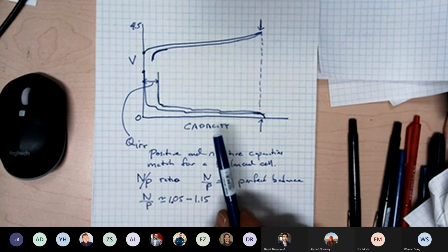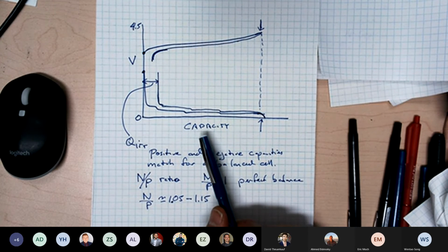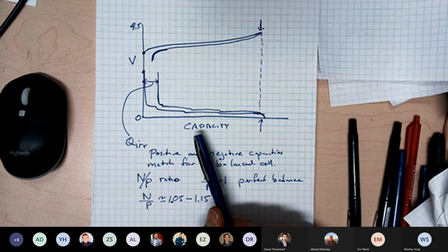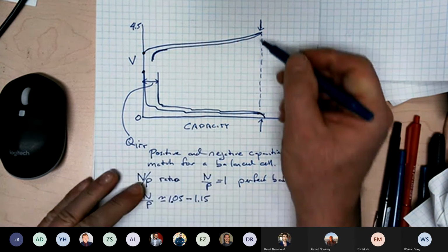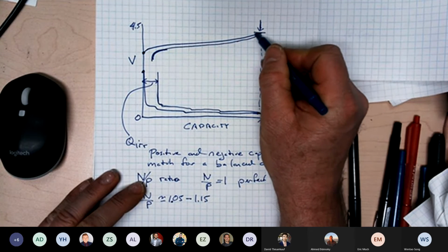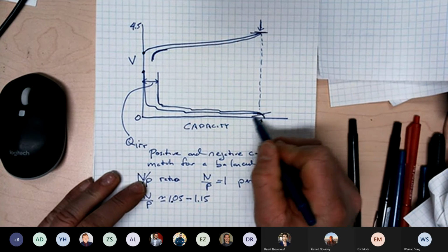Okay, so this is what happens during the very first charge of the lithium-ion cell. This is what's called the formation cycle, and this is done at the manufacturer. The formation cycle is usually done at elevated temperature and under a relatively moderate charging rate, because you want the positive electrode to be in equilibrium at the voltage to which you're going, and you want the graphite to be in equilibrium at the voltage to where you're going.